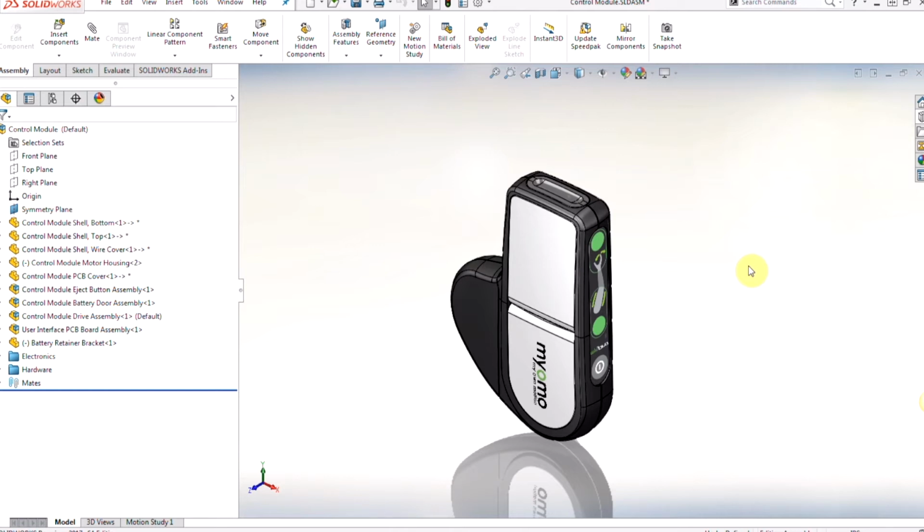And today we're going to be diving into the last video of our three-part series about SolidWorks 3D Interconnect. In part 2, we took a look at how to directly open the third-party CAD data so we can add our own SolidWorks features and then update it with the newer version. In this last video, we're going to explore how we can import a Solid Edge assembly. Then we're going to break the link to the original third-party CAD file, utilize feature recognition so that we can fix up our components without having to wait for the vendors.